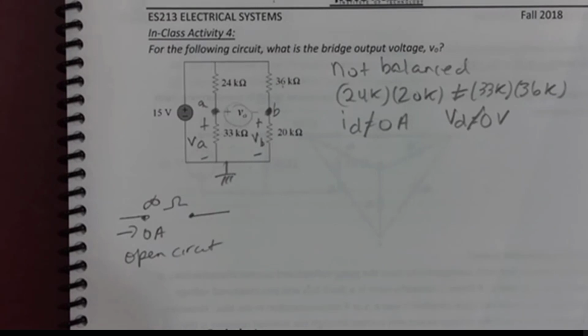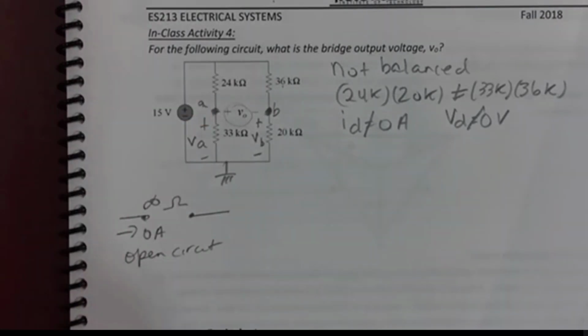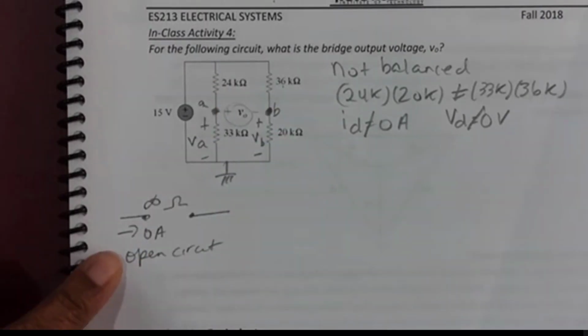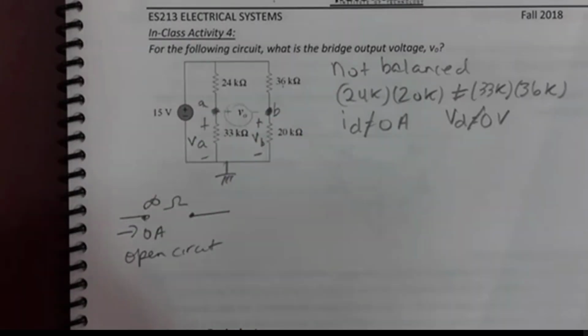If they're connected, or are they not? They are connected in the middle, and that's what series means: exactly two things meet at a node. I thought that... It's a voltmeter. That's not a connection point of any circuit element. That's just me putting a voltmeter right here to measure the voltage. And it's modeled as infinity, so even if I did model it as a resistor, it's open. It's an open circuit.